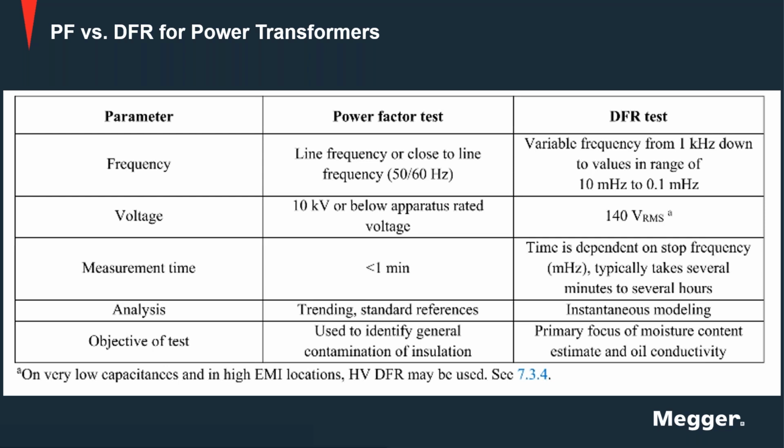But when we look into DFR, we only apply 140 volts RMS. This chart is taken from the DFR guide published by IEEE, and you can see that it's stating here that if you are working in a location with high electromagnetic induction, high voltage DFR might be used.